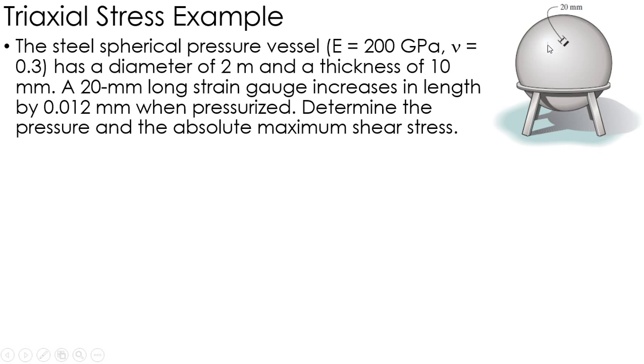Okay, I've got a little strain gauge put on there, 20 millimeters long. It increases by 0.012 millimeters when this thing's under pressure. Okay, so from that, I want to figure out what the pressure is. Also, what is the absolute maximum shear stress?